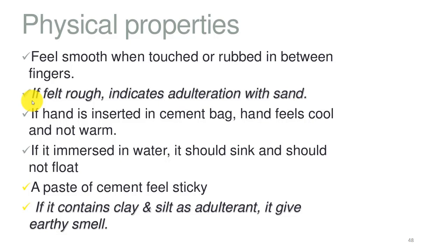Thirdly, you can feel the cement on your hand by rubbing between your fingers. It must be smooth. So the cement is pure. You can also immerse the cement into the water. It must not float, it must sink because the specific gravity of a cement is much higher than the water. The specific gravity is around 3.15.